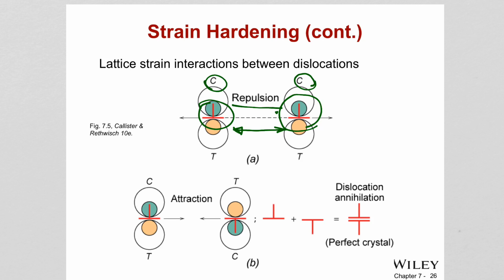compression will always come together with tension in order to neutralize those strain energies, because at the end you are creating energy by straining. Remember, under the stress-strain curve we said energy is stored. So if you are stretching the bonds, you are storing energy, and the material wants to eliminate those stresses and energies inside.